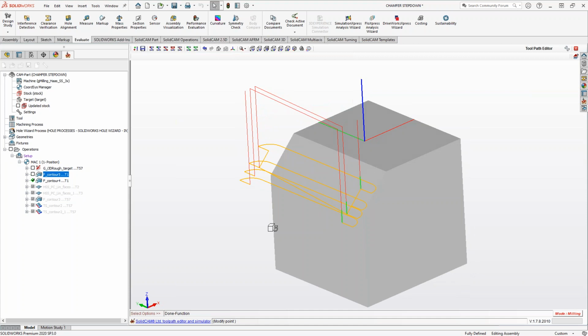Now, I tried this when I was creating the video, and I don't think you can click on sketch points here. You can only realign everything using the data points from the original toolpath. That's what I saw. But if anyone knows better, or if there's any follow-up and there is a way to use sketch points, we can easily revisit this in a future SolidCAM session. But it looked to me like you're only using this to edit the existing toolpath. So you can delete what's there, or you can only add from what's there.